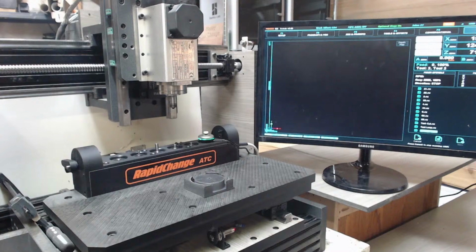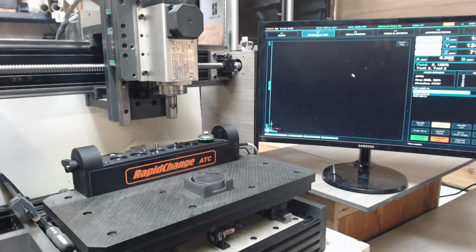So now we're going to loop the same file. This is just a program that's going to loop this same file 5 times. Test loop 2. M98 is calling P50, which is the file I just ran, 50.nc, and it's going to loop it 5 times. I know you can't see the screen there, but that's what it says.